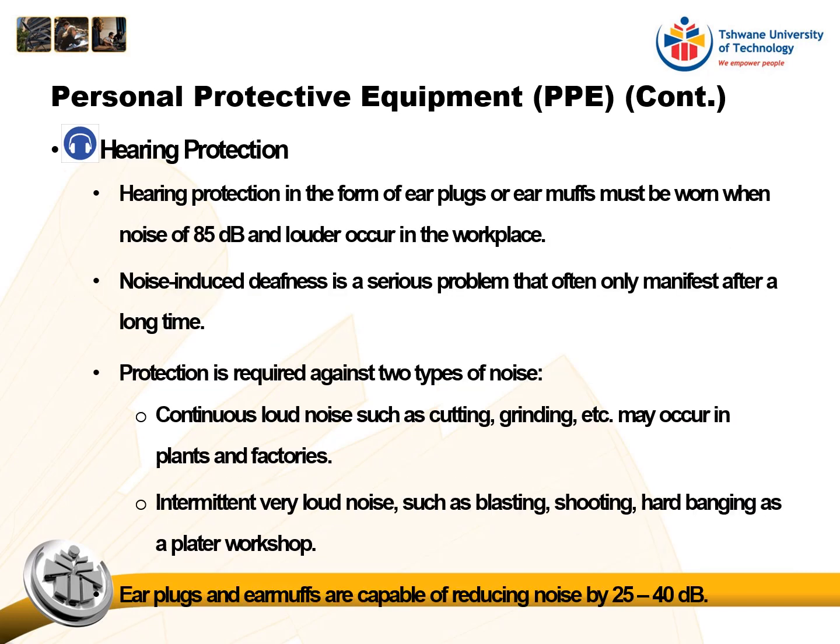Hearing protection. Hearing protection in the form of earplugs or ear muffs must be worn when noise of 85 decibels and louder occurs in the workplace. Noise-induced deafness is a serious problem that often only manifests after a long time. Protection is required against two types of noise.